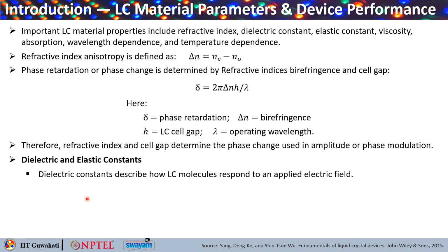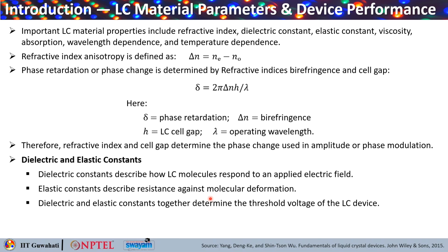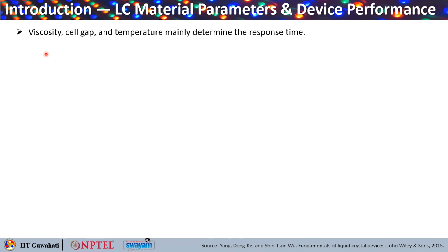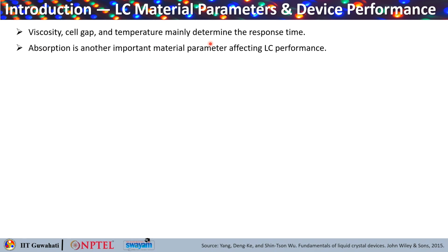Now let's look into the dielectric and elastic constants. Dielectric constants describe how your liquid crystal molecule is going to respond to any applied electric field, whereas the elastic constants describe the resistance against molecular deformation. So if you take the dielectric and elastic constants together, they determine the threshold voltage of the liquid crystal device. Then other parameters like viscosity, cell gap and temperature mainly determine the response time. So how quickly or how slowly your liquid crystal is responding to the change in